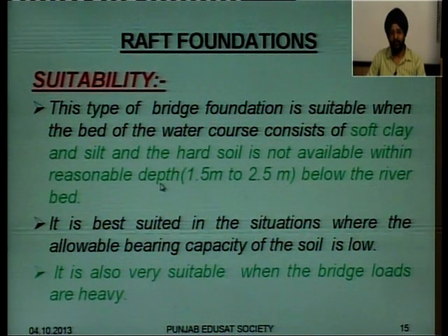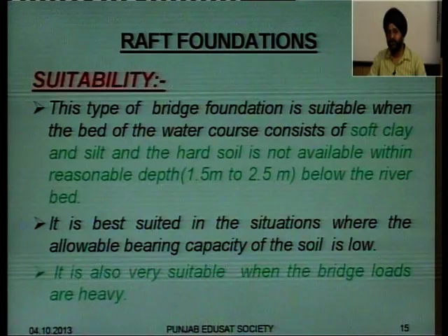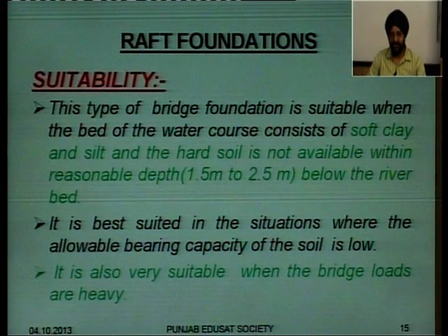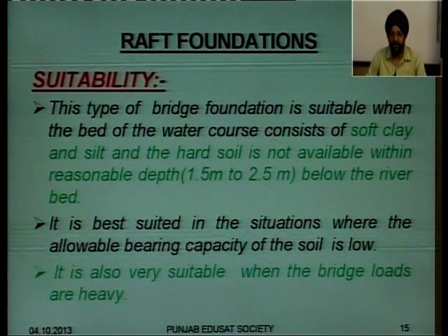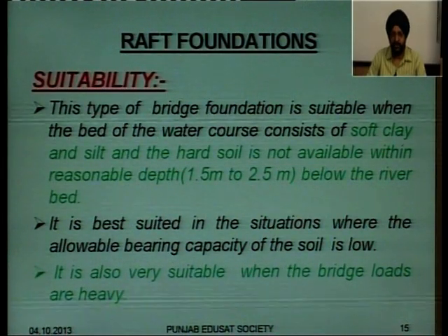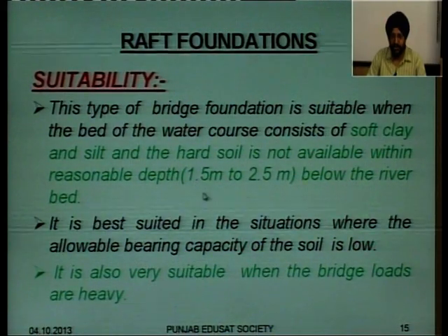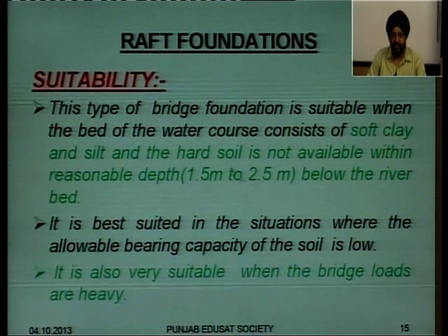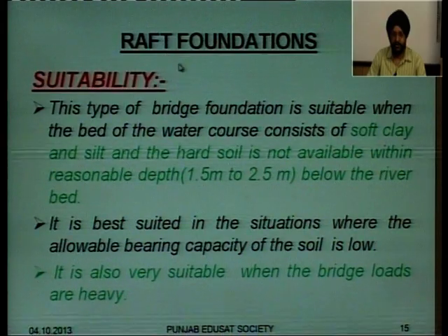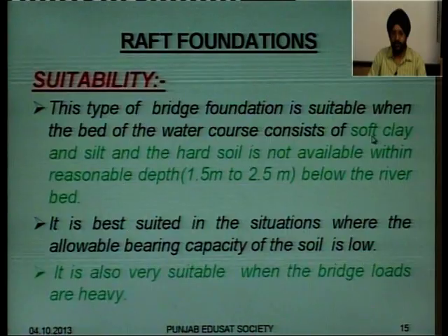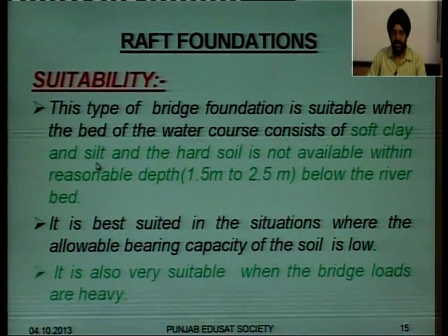So we can say the raft foundations are best suited for a soft clay and silt base, where we are not having the hard strata, hard soil. If we are not getting hard soil up to this much depth below the river bed, these are the best foundations. We can provide raft foundations if it is a soft clay and silt bed.